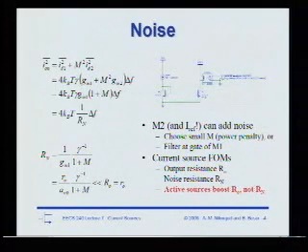Okay, but let's say that my uncle is in the resistor business, so I have access to big resistors. What's another reason I wouldn't use it? It's noisy. No, we just showed that it's not noisy. Actually, a big resistor is good, right? It would contribute very little noise. It's better. From a noise perspective, a resistor is better. Voltage headroom. Yeah, voltage headroom, right?